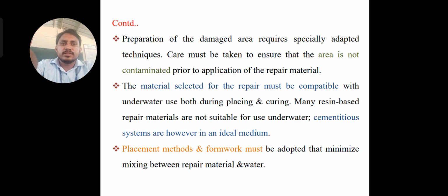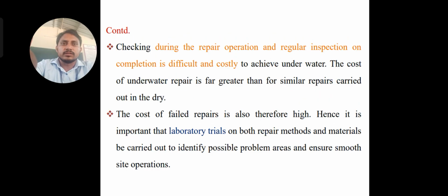Mainly cementitious systems are adopted, and placement methods and formwork must be adapted to minimize mixing of repair material and water. Checking during repair operations and regular inspection on completion is difficult and costly to achieve underwater.